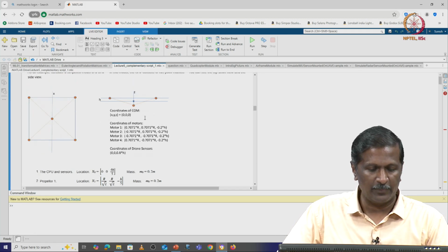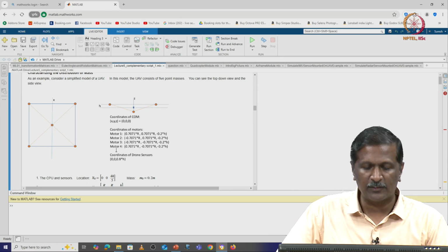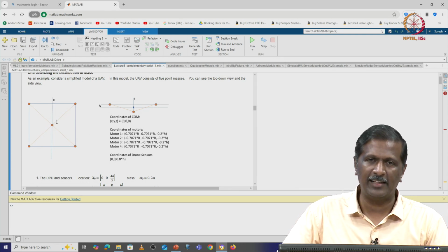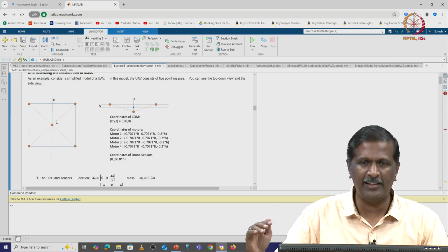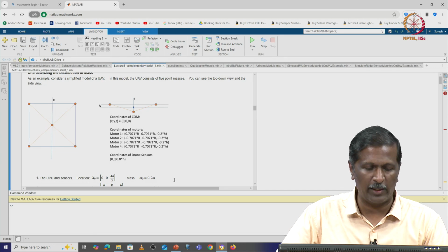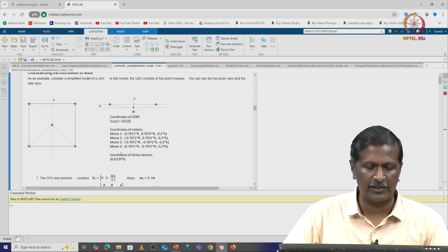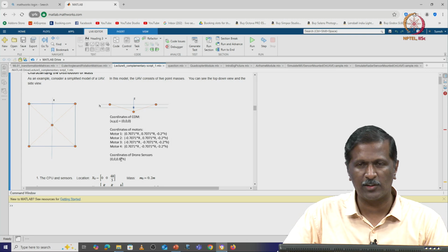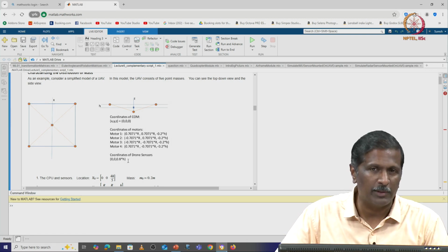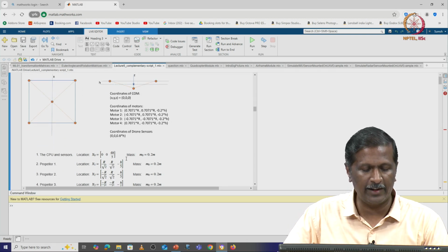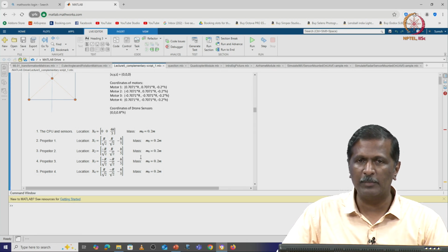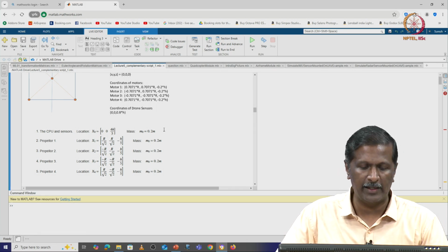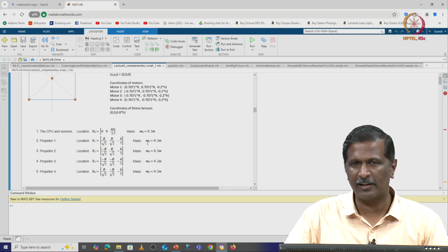Now, the sensors, whatever I am doing, may not be exactly at the center, right. We may be putting the battery and everything slightly at a different height, whereas they are not displaced in the XY plane. That is a coordinate where I am going to keep my sensors, I am representing at 0, 0, 0.8 H. So, this you need to measure, this information you need to add, right. Moment I do that, I have my x naught, I have my x1, x2, x3, x4. I have to mention what is my mass of the motor propeller plus ESC. I am just putting it here just for a reference here, right.